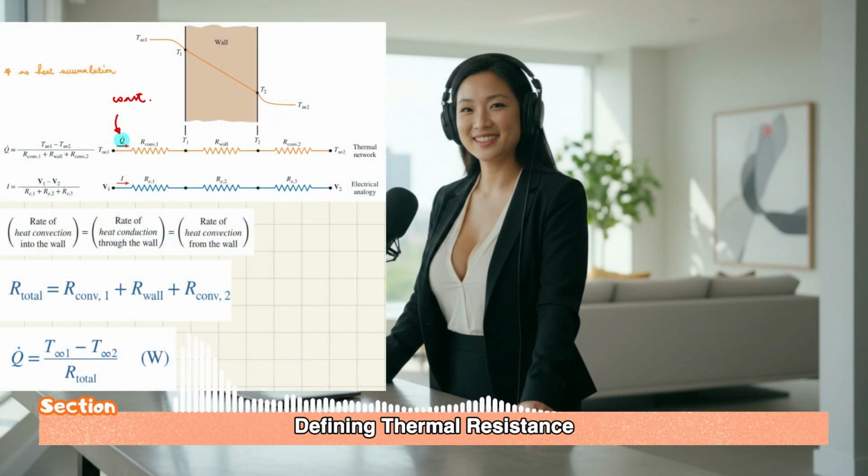So Q dot conv1 into the wall equals Q dot cond through the wall equals Q dot conv2 out of the wall. And because the flow rate is constant, the resistances are in series, just like current flowing through several resistors in a row. Which means the total resistance, R total, is just the simple arithmetic sum of the individual resistances. R conv1 plus R wall plus R conv2. And that gives us our master equation for solving the whole problem. Q dot equals the total temperature difference divided by the total resistance.